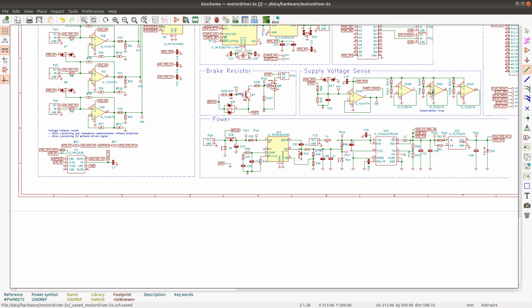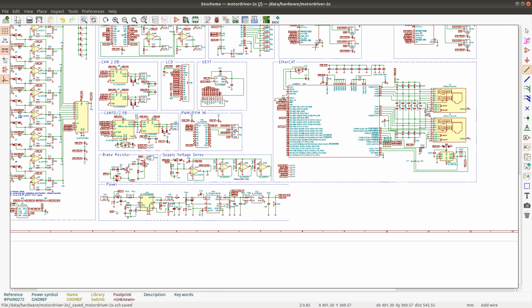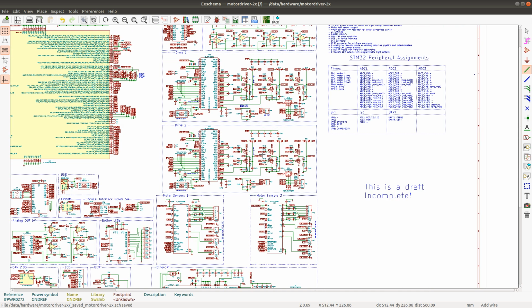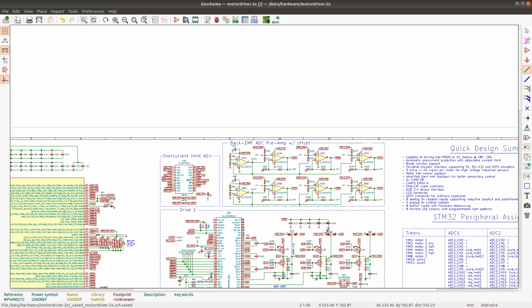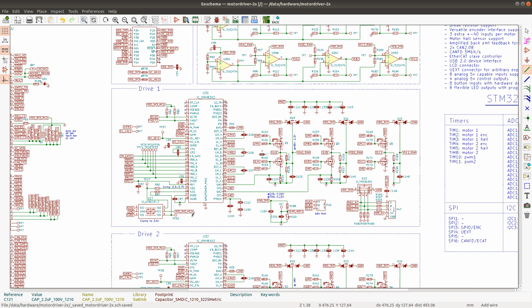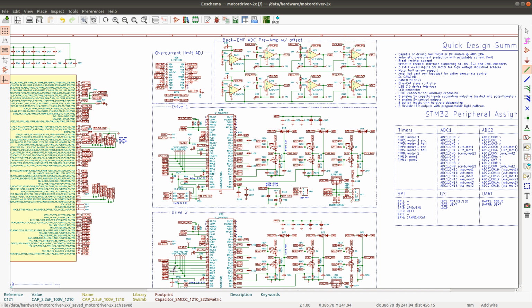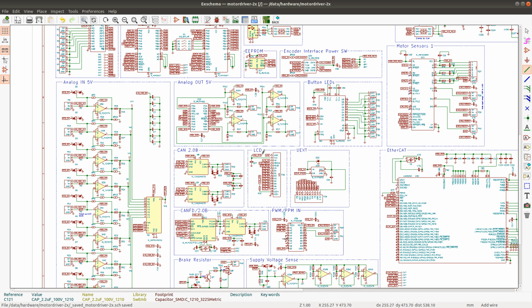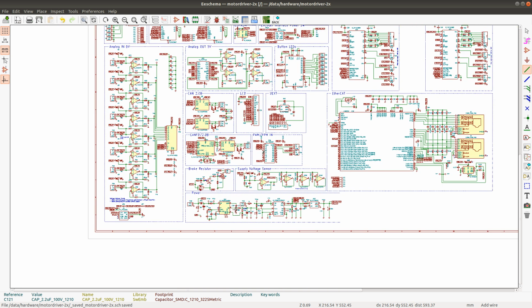What can we reuse in this circuit? I think I do have the capacitors I could reuse, and I got them here. So I have several ones here. I have the 220 63 volts, and I have 2.2 100 volts. So I'm going to use 2.2 100 volt capacitors. And that would be pretty much just like what they used in the example.